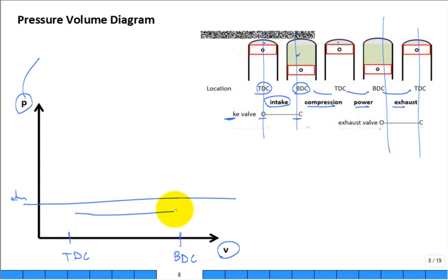If you spray it along that crevice and the RPM of the engine zooms up, you just discovered where your vacuum leak is, because as you sprayed it, it got sucked in at that point. It's not supposed to be sucked in along a leaky gasket. Or if you spray it and nothing changes on the RPM of your engine, then you know. What do you spray in there? Like a starter fluid? Yeah, starter fluid. It's actually an excellent way to diagnose problems.